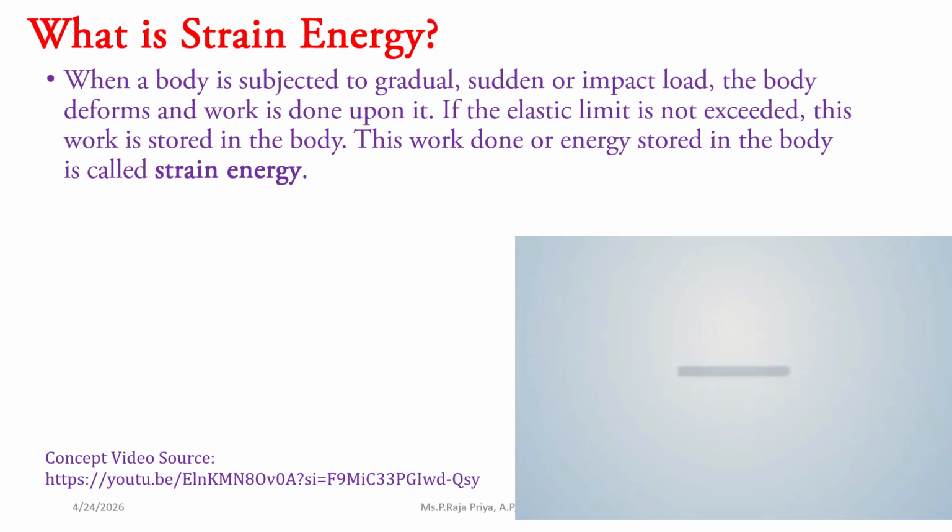Strain energy is an energy which is stored in a body when it is subjected to some kind of external loading within the elastic limit. So when a material is subjected to external loading, either a gradually applied load, suddenly applied load, or impact load, but within the elastic limit, the body deforms so that some work is done on it. During that time, the body will store some energy. This stored energy is called the strain energy.